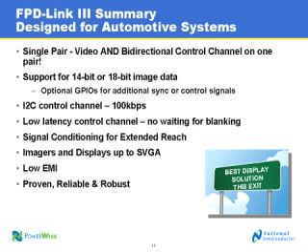What's done when the system is set up, you'll configure the deserializer, set some registers to let it know what slave devices are out there. And you can have, I believe it's up to 8 slave devices. So whether they're cameras or additional devices, temperature sensors, FPGA, anything that you need else, there. Any other I2C slave devices can be addressed directly by the controller, and then that data is routed through the deserializer serializer pair, and then back to those slave devices.